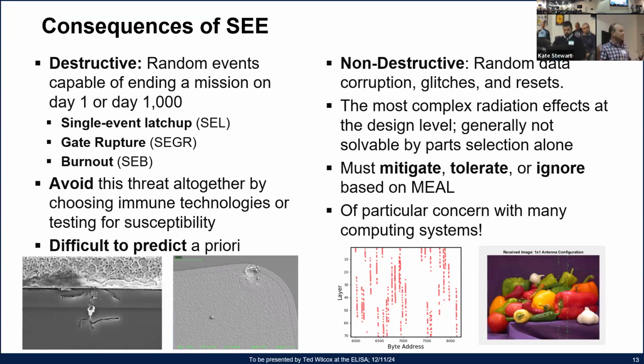And so you can see very physical destructive effects that have happened to some of our power. I believe those are power Schottky diodes, actually. These streaks here, this matrix looking thing, is a 2D projection of a 3D visualization of single event upsets in a 3D NAND flash. So vertical is actually depth in the material. So the streaks you see are actually single particles passing through the multiple layers of the 3D memory.